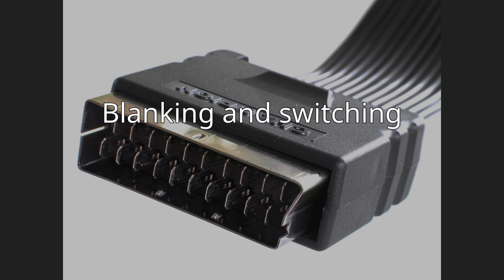0V to 2V means no signal or internal bypass. 4.5V to 7V, nominal 6V, means a widescreen 16:9 signal. 9.5V to 12V, nominal 12V, means a normal 4:3 signal. Pin 16, the blanking signal pin, carries a signal from the source that indicates that the signal is either RGB or composite.